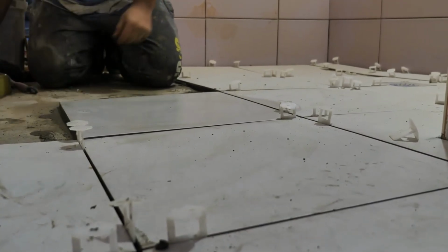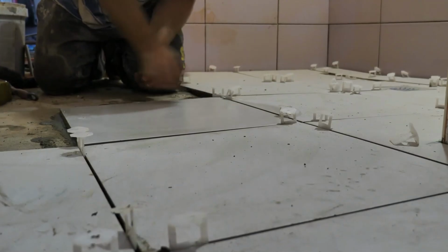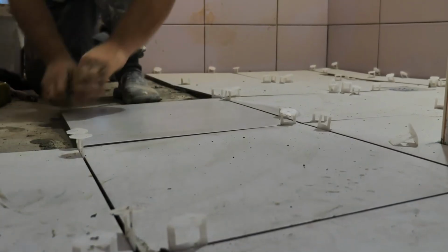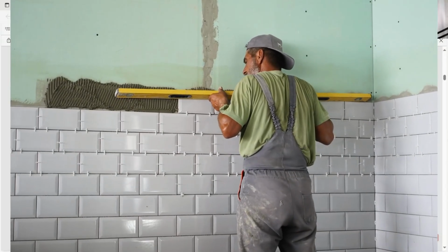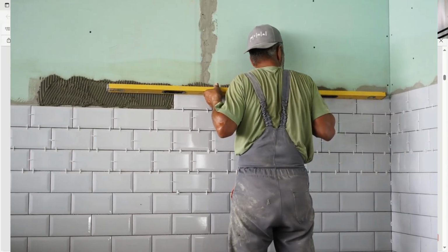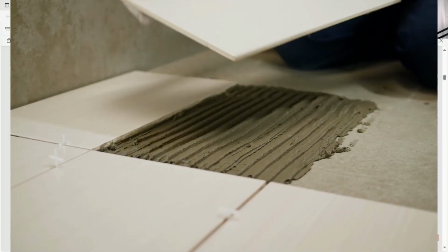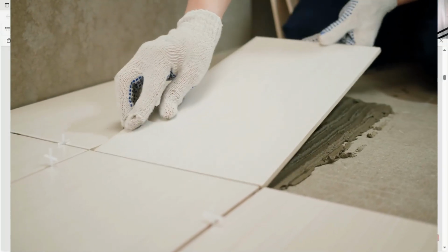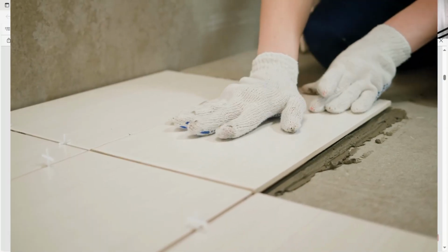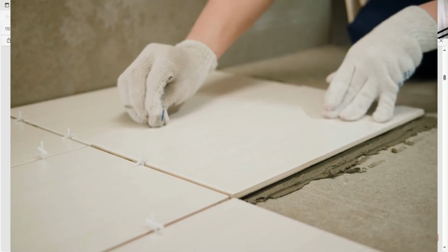Here the note is given that if level variation on the floor or wall is more than an average of 12 mm in 3 m length, excluding intentional slope for floors provided for flow of liquids or the drain point, surface preparation as required to bring the surface true to plumb and level shall be taken up with the appropriate material. So the code has given the provision that we can go up to 12 mm, and if it is more than 12 mm, then you need to make the surface true to plumb and level before fixing the tiles with the tiles adhesive. So these are the things.